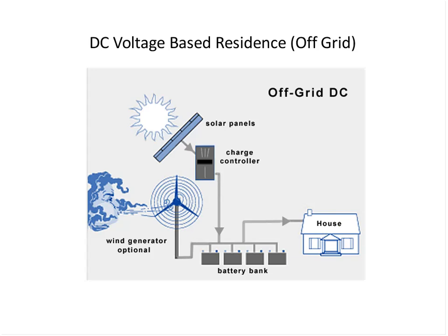So you could have a very clean copper running DC in the house, so your ohmic losses are very low. You can avoid the double conversion. You only convert once from AC to DC for the wind. Because ultimately, if you look at electronics in the house, again, it requires DC voltage. So you're going to AC and then you're converting again to DC in the devices themselves. So if there were a new class of appliances built that were DC to begin with and not AC, you could have a very efficient house, and you could simplify the wiring, and you could reduce cost. But it's going to take a while. This is a vision of the future.